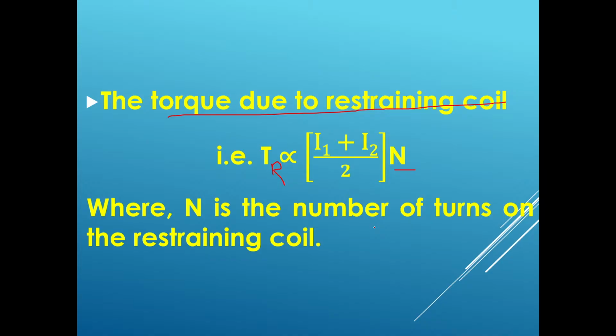So the operating characteristics of this relay, except for the effect of the control spring, that is the counterweight at the lower currents: the ratio of the differential operating current to the average restraining current is always fixed. The ratio of the differential operating current to the average restraining current is always a fixed percentage. That's why it is called a percentage differential relay.